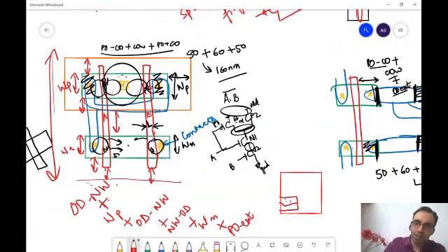Okay. So I will do PO to PO by 2. Why by 2? The minimum spacing is what we have to ensure, right? Yeah, because if I leave half DRC here and half DRC in the other cell, overall full DRC will be met. So the other PO is of the next cell you're talking about. Yes.